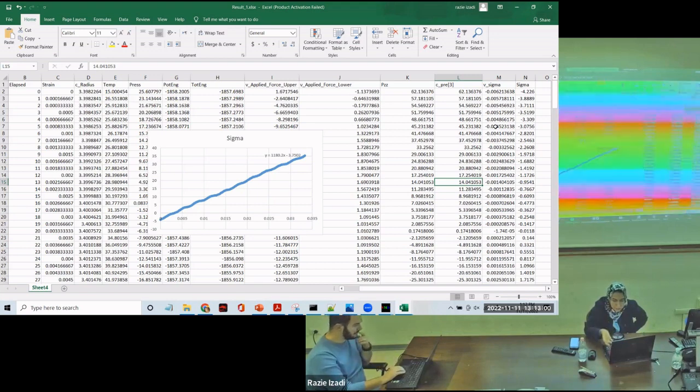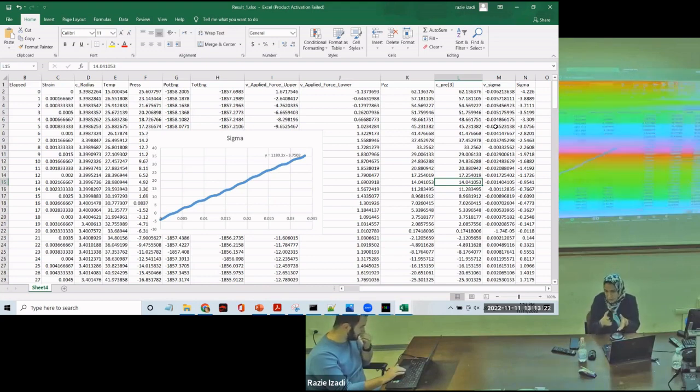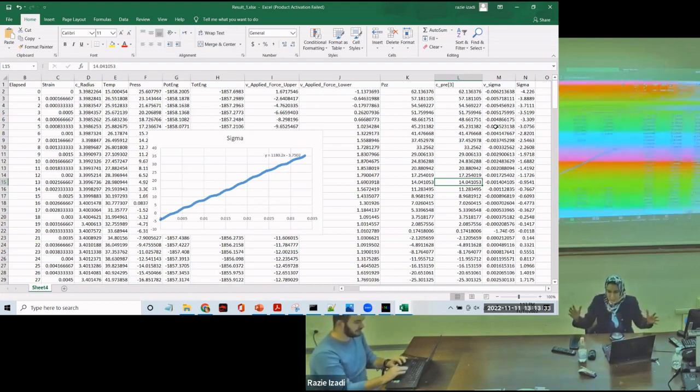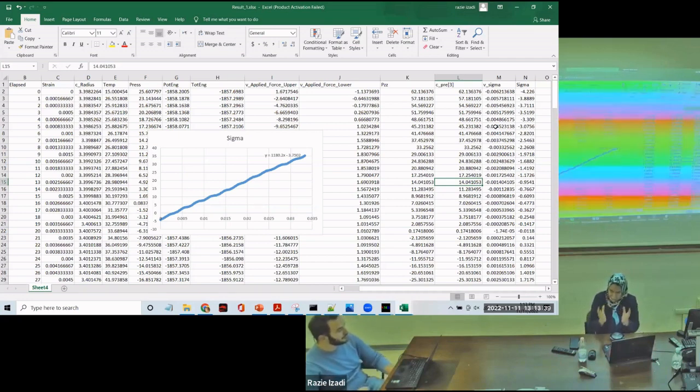But that is for nanoparticles that are made of metallic or metallic oxides. If the structure is really more complicated, it's a good idea to start from a rectangular simulation block, or even the one that I told you can have more faces, nearer to the droplet, and then you can increase the simulation box without mapping the atoms, and then you do the relaxation so that it forms the droplets.